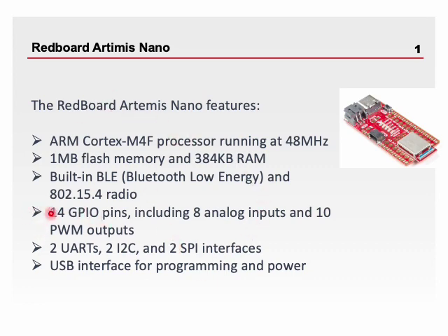For example, GPIO, which stands for General Purpose Input-Output, are pins with the capability to be configured to serve as either digital inputs or outputs. They allow the microcontroller to interact with the external world by sending and receiving digital signals.